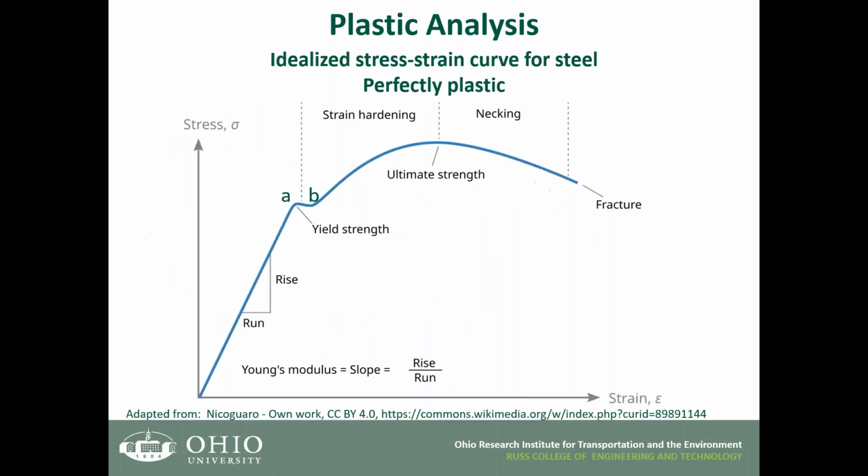Okay, to explain those equations, let's look at the stress strain curve. On the stress strain curve, steel goes up to point A as linear elastic, then from A to B it goes plastic. In that zone AB, you can experience a significant amount of strain without failure. So that is very important. Let's go next.